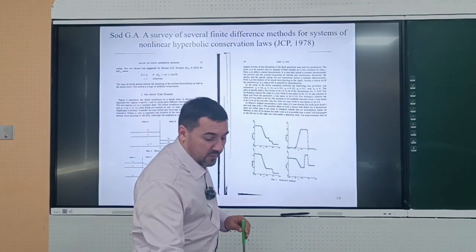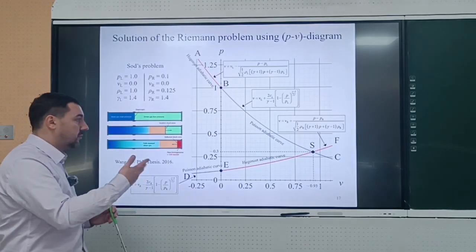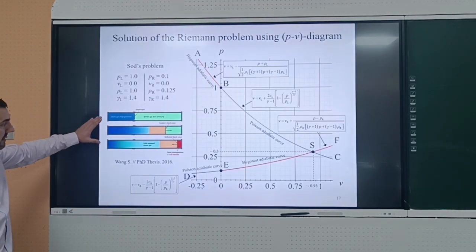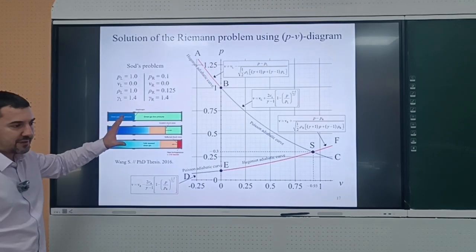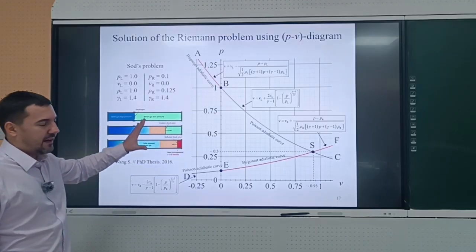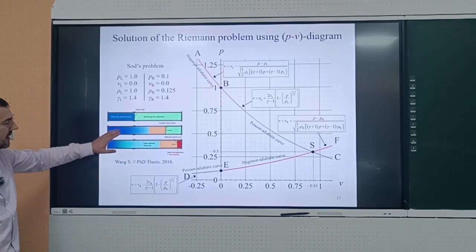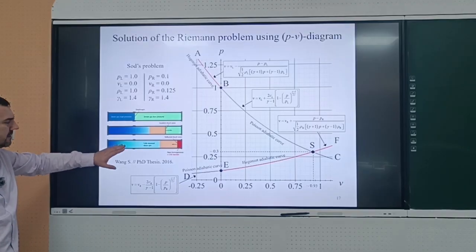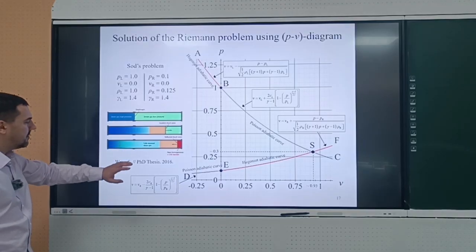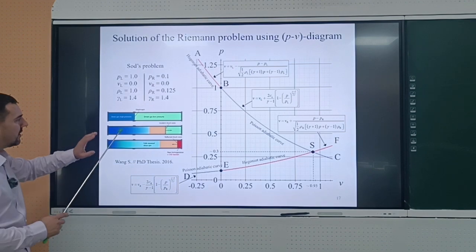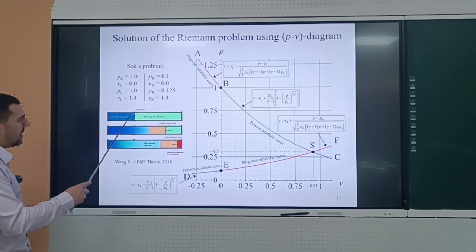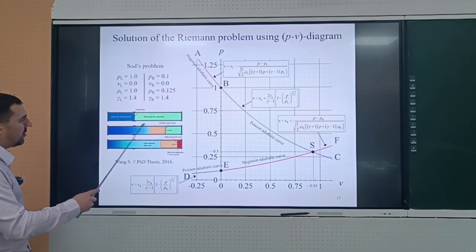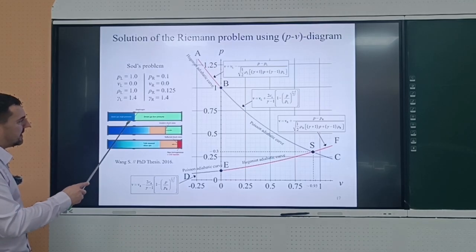But anyway, why is it called the shock tube test? Because, as I already mentioned, the closest analog to a physical interpretation of the Riemann problem, if you take into account shock physics, is a shock tube. This picture is from some PhD thesis, and it's very beautiful. The shock tube is just a tube with a high pressure chamber and a low pressure chamber, and a diaphragm.